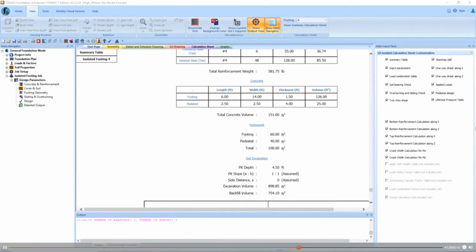So in chapter 5 of the book, there's some information related to passive pressure. When we're talking about passive pressure, we're talking about when we have a lateral force on our structure, like we did on the substation structure. That lateral force is pushing the foundation into the soil. Since it's pushing the foundation into the soil, there's a resistance from the soil itself.